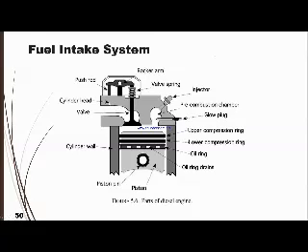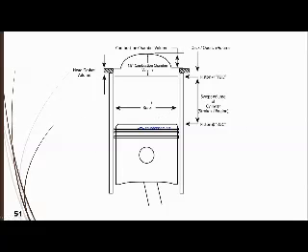So okay, this is the schematic diagram of the diesel engine. Again, I would like you to look at the positions we call TDC, which stands for top dead center, and BDC, bottom dead center. This is where the volume of the engine will be calculated. For example, if you have a 2000 cc engine for a car, how they calculate it is basically the cylinder area times the height between these two. That's how we measure it, same for the tractor and other mechanical engines.